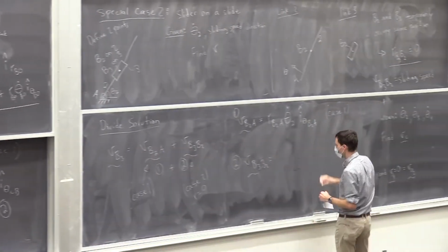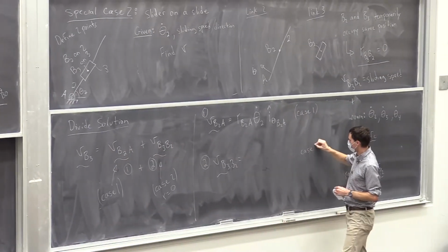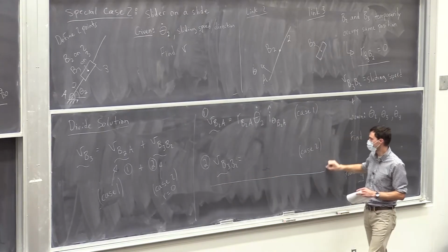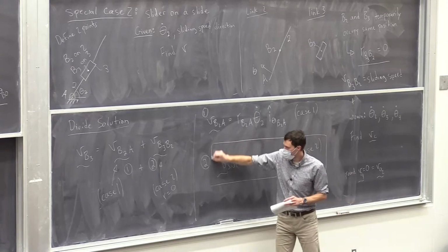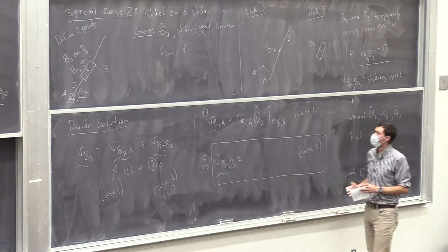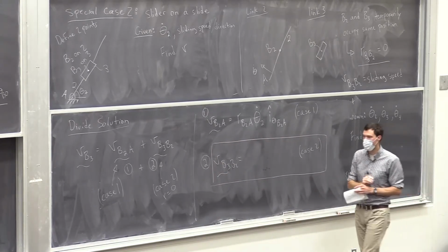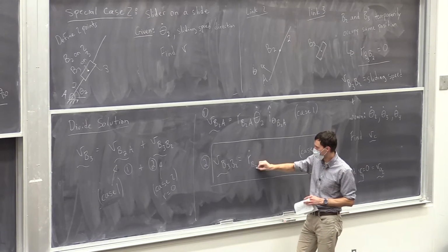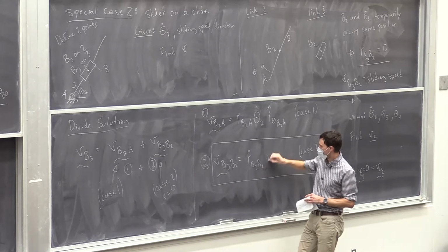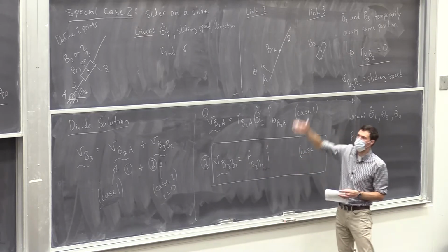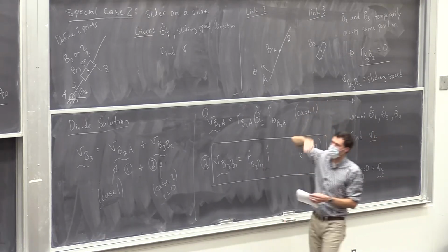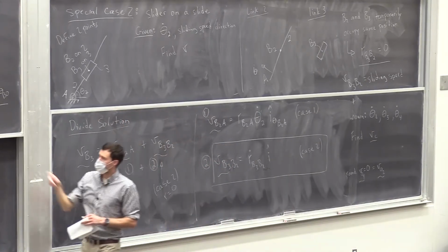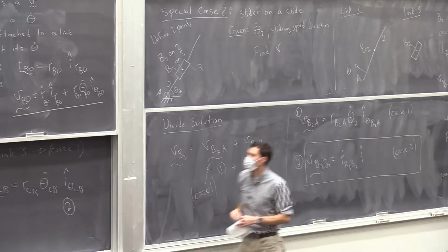That's our case 2. You can sort of underline this as your case 2 scenario: 2 points on a slider. You can define them at the same location, and all we're left with is the sliding speed. And of course, it's in the sliding direction, which is kind of obvious. It's sliding along the slide, and we'd call that the radial direction.